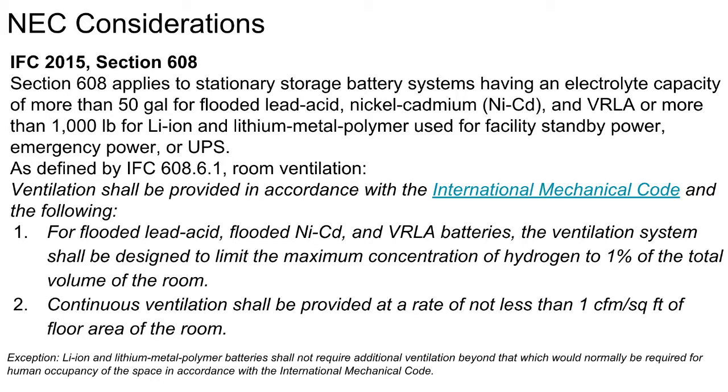That's where on a sealed battery you don't have these ventilation requirements. This is only for flooded lead acid, nickel cadmium, or a kind of lead acid battery called valve regulated lead acid, which produces less emissions than flooded lead acid. It's kind of a compromise between a sealed and an unsealed battery, and it's more expensive and it has a shorter life.